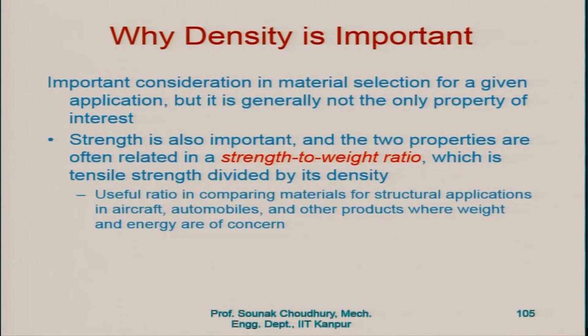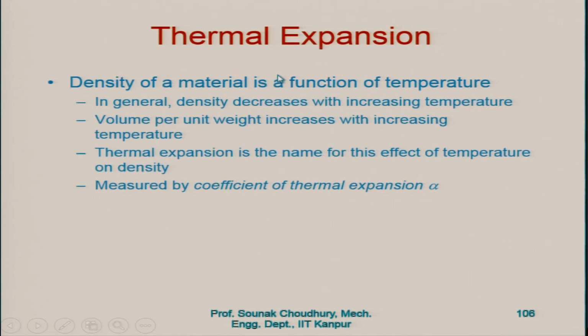Why is density important? Because it is a consideration in material selection for a given application, but it is generally not the only property of interest. Strength to weight ratio is more important in this case, which is tensile strength divided by the density. Thermal expansion: similarly, density of a material is a function of temperature.